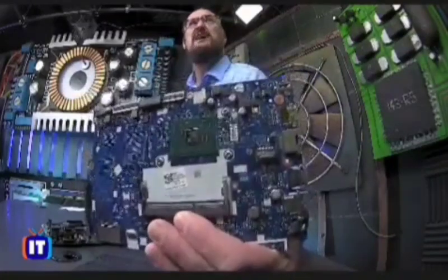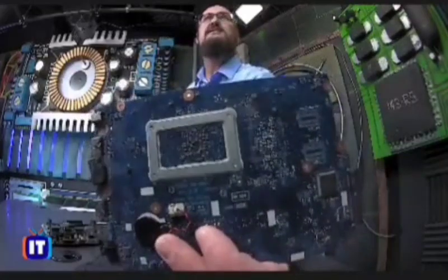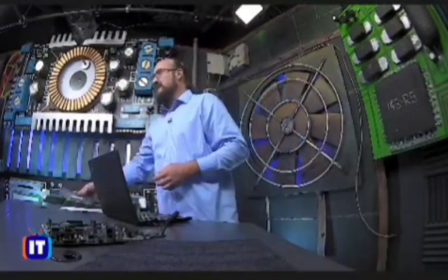You can't really see anything, right? We have a CPU that quite literally is embedded into the PC itself, right? We're not taking this out. If we try to take that out, we're going to cause irreversible damage to the motherboard. So with BGA or ball grid array type implementations, understand that that is literally embedded into the motherboard itself versus the ones that aren't, like the LGA and the PGA. If a CPU fails, you can replace it. Embedded BGA-based CPUs, if they fail, you typically have to replace the entire motherboard.